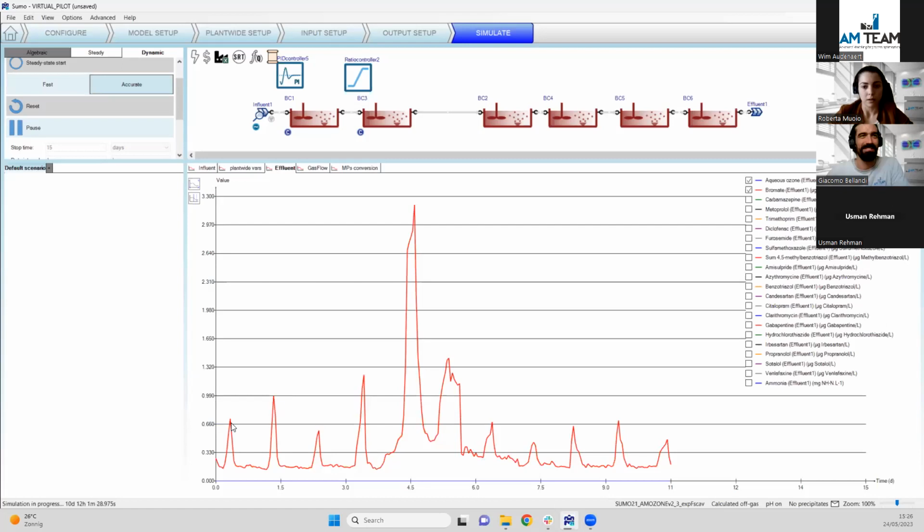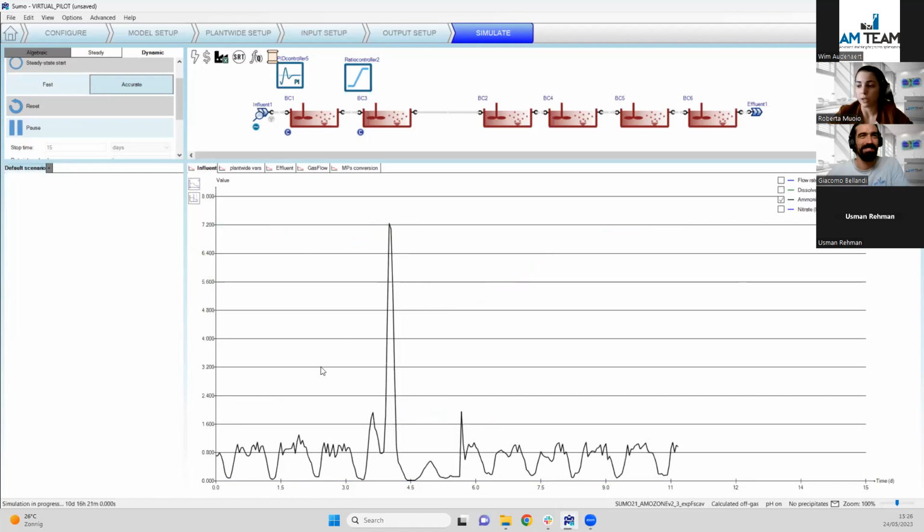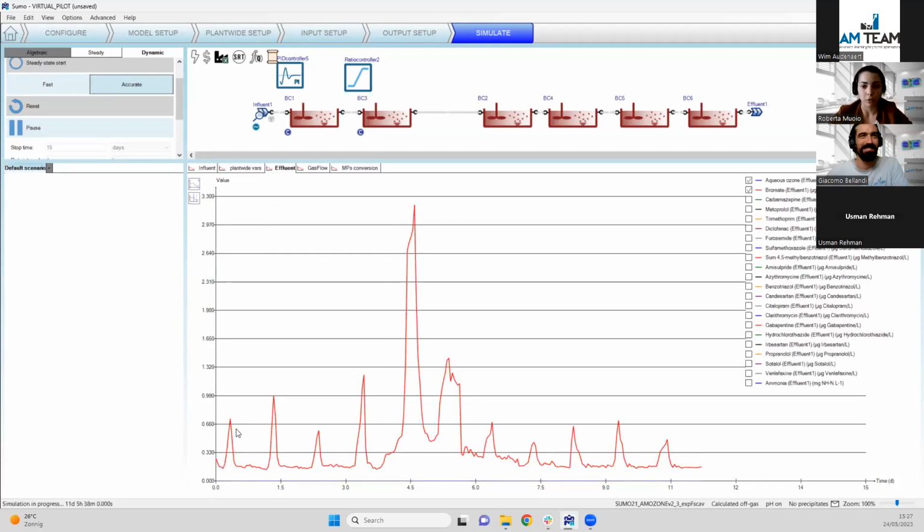First of all, we can ask ourselves why we have this increase in bromate during the dry weather condition. And we can find an answer if we look deeper into the ammonia dynamics. You can see that at certain moments of the day, the ammonia concentration goes very low. And we know that ammonia has an important role in the bromate formation chain, because if ammonia is present, it can sequester the hypobromous acid to form bromamines, preventing the bromate from being formed. So when ammonia is lacking, then bromate peaks can appear.